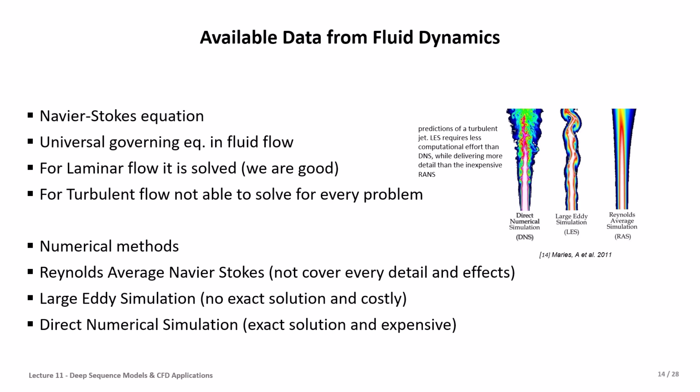The other one is the CFD. However, CFD for turbulent flow, as we discussed before, provides an averaged result, so the data that we have with the average doesn't carry all the information from the flow. LES also, as we said, is solved based on a specific size of the eddies, and then it computes the smaller scale, which is not an accurate solution. But DNS is the most accurate solution in the CFD. Therefore, to have reliable data from the CFD, the DNS data could be used.